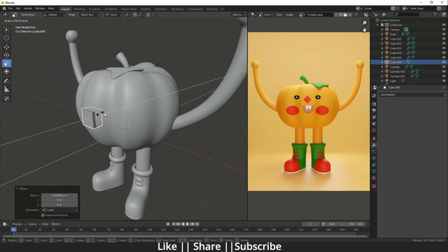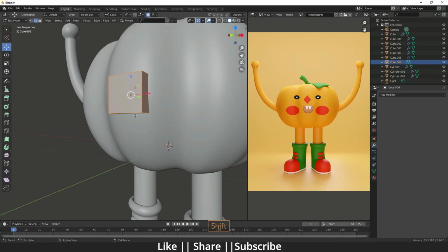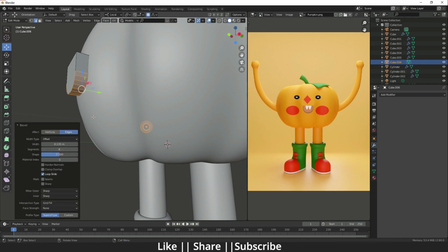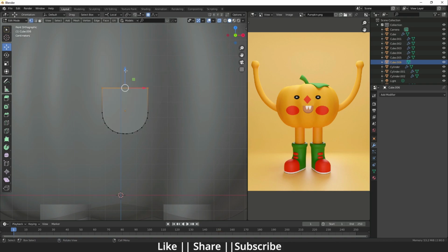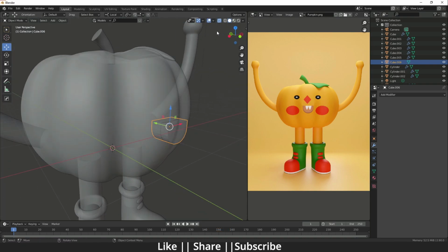Then I'm just going to scale something like this, and after that make sure you apply the scale. Then you have to go to the edit mode and select the side edges, and then do Control B for bevel and add some edge loop here. Yeah, I think that's fine, looking fine to me. And then you have to switch to the X-ray mode and move those vertices downside, so it's looking like a mouth shape.